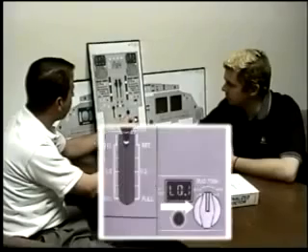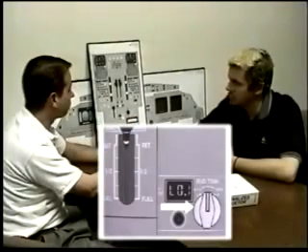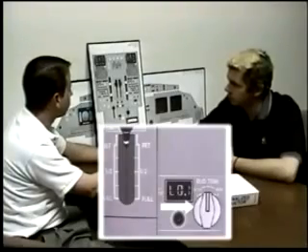In an A319, we can get up to 30 degrees trim, and so that'd take approximately 30 seconds to get full rudder trim. According to the UAL flight manual, it says that the autopilot can provide 5 degrees per second, although I rarely see it go much more than 0.5. Autopilot's engaged. Will this manual trim switch work or the reset work? No, I can't manually trim when the autopilot's engaged, or even reset.